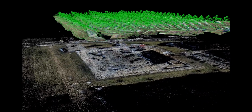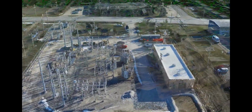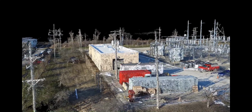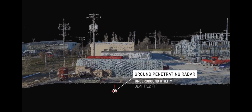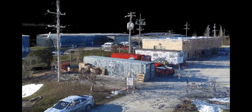Acquiring site data with UAVs minimizes the need for site access and greatly reduces time on site. The photographic data is converted to 3D data using a technique called structure from motion. Other data sets can also be included in the model, such as subterranean obstructions identified with ground-penetrating radar. The model is then mapped to geospace through a handful of traditionally surveyed ground control points.